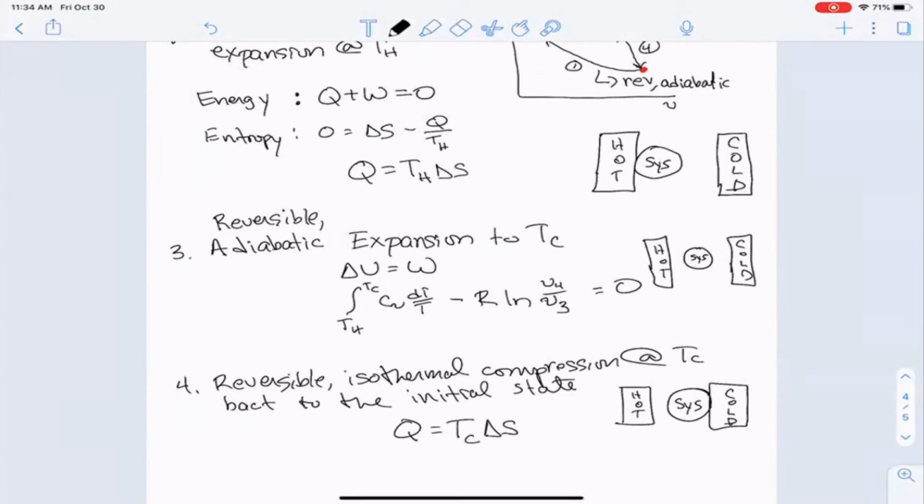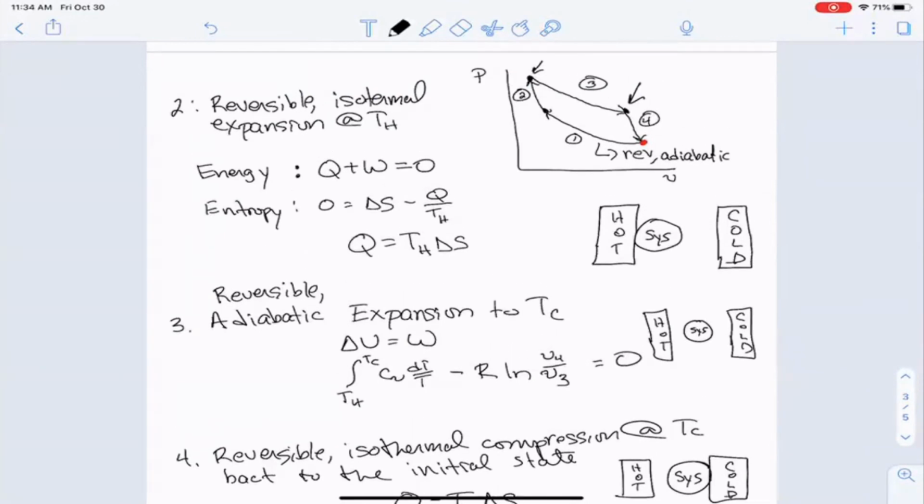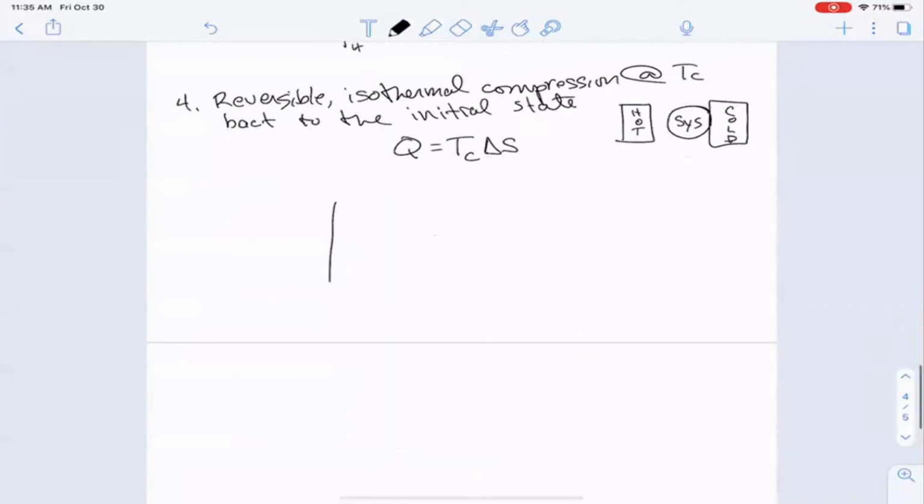Okay. Now, the interesting thing is that when you've seen cycles before, or at least the one time that we've had an example on it, they look a lot like that, where you go around and you're used to asking yourself what is happening from the perspective of pressure, volume, and temperature. For some of these cycles, another way of thinking about this is also very helpful. And so we're going to draw something called a temperature entropy diagram. And it's helpful here because every step occurs at either T hot or T cold. And we also have reversible adiabatic steps, which are done at constant entropy. So we have 2 states of entropy here.